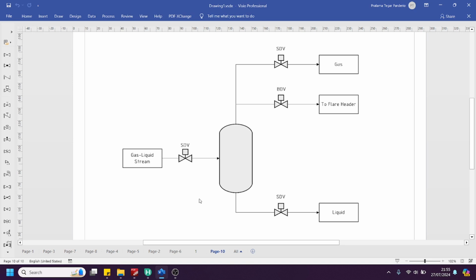Hello everyone, so today we are going to develop a model regarding the pressurization of the vessel during an emergency fire case. In an emergency fire case, the safety system, or logical safety system, will induce the SDV, shutdown valve, to be closed and isolate the vessel. Therefore, in order to reduce the possibility of failure of the vessel, the depressurization system should be applied to this vessel by releasing the inventory, commonly consisting of gas.